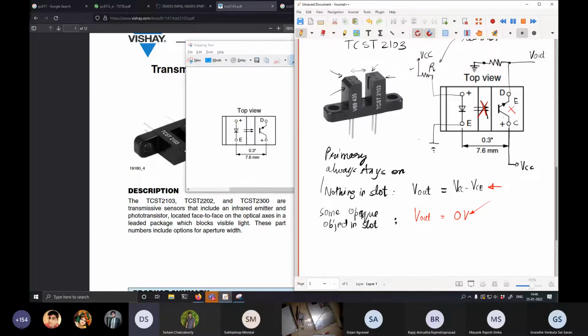No, if this gets disconnected, well, let me draw an equivalent diagram. So you have VCC, then a switch, and this is going to a resistor and ground, and you are measuring this voltage. Now tell me, when this switch is open, what will be the voltage? So 0, sir. Understood, that is exactly what we've written.